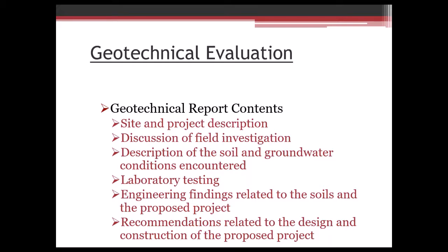The other thing that's important that goes into the report is discussion of what we did for the field investigation. Basically how many borings we did, how we advanced them, how we sampled them. Then we do a description of the soil and groundwater conditions at the site. And this is a written out description of basically all the information that's on the boring logs. And it gives the reader an idea of what's going on the site. Maybe for those that don't understand a lot of the boring logs or need some quick reference for a project.